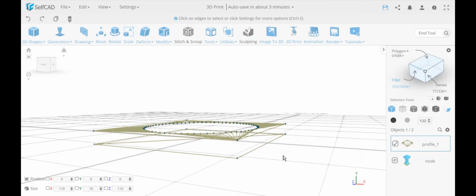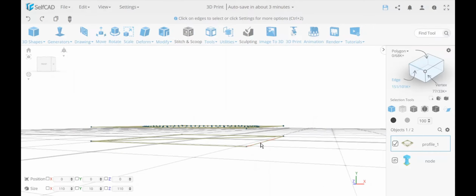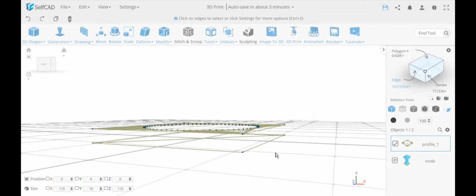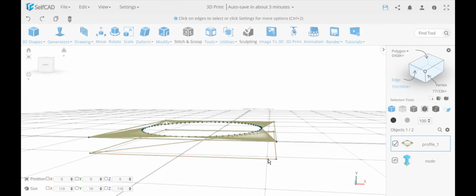So let's say the distance between here and this is 20, and the material thickness is 10. So we will have 10 going below here, 10 above, and then 10 from this going down, and then this will fill the gap. So this is basically the idea of a slicer. It creates slices. Each slice is a 2D layer, and then the material fills it.